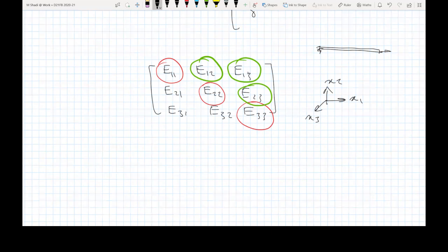And then you have the shear component. The meaning of the shear component is, if you have two vectors in the original configuration, and then you move to the new configuration, there will probably be a change in the angle. I probably should not use x1 and x2, so as not to confuse you. Let us assume that you have n and m, two vectors.